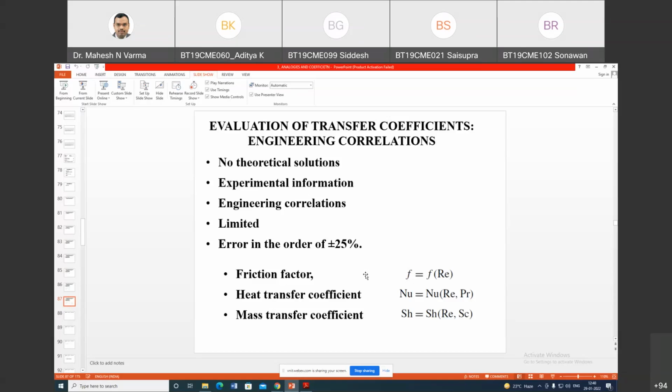If say the thickness of reactor needed is 1 centimeter, you could use a thickness of 50 centimeter, because I don't know the values. But now I know the error is plus minus 25%. So if thickness is coming to 1 centimeter, I can add a 50% margin, so 1.5 centimeter I can use. But I know that my design will never fail in that case.